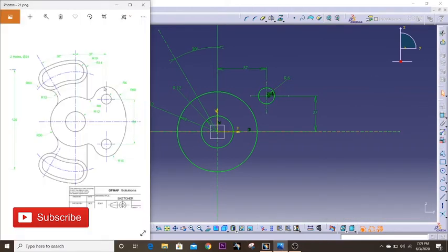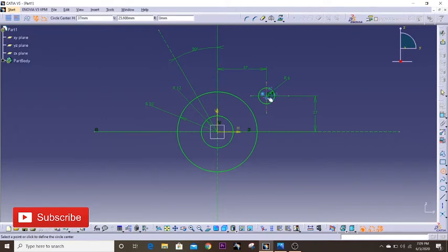So we also have this circular arc. I'm going to make a complete circle just north of it, and I'm going to trim off the rest of the parts. The radius of this is 15 millimeters from this point.